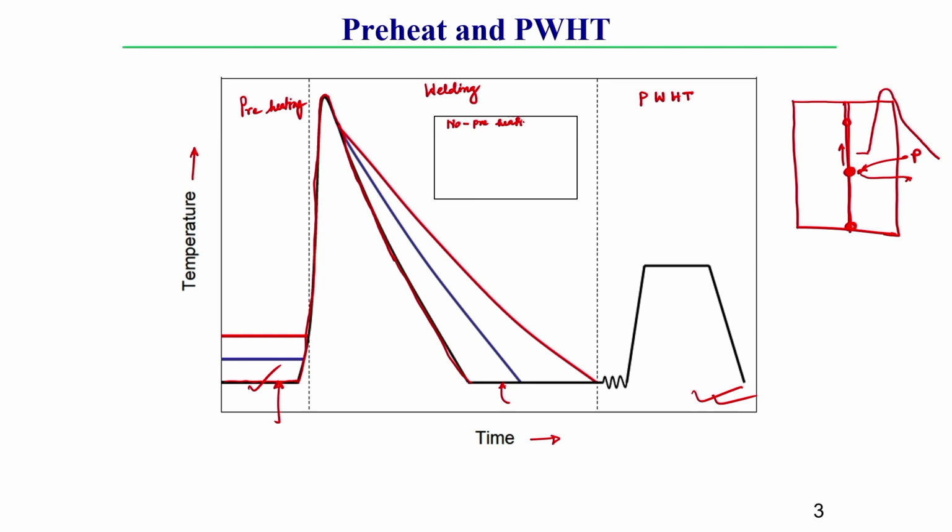No, here you can see, because here the preheating temperature is ambient temperature, no extra heat is applied. This second curve, the blue curve, represents an initial temperature, that means some initial preheating temperature we provided. This is generally called the medium preheating curve.